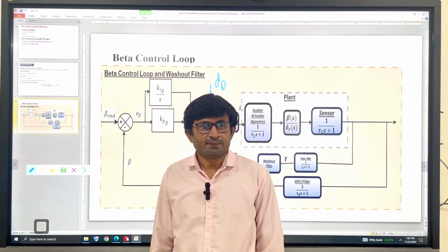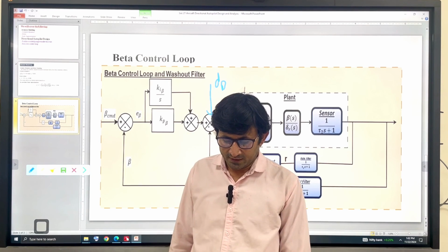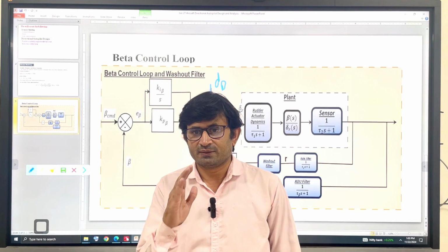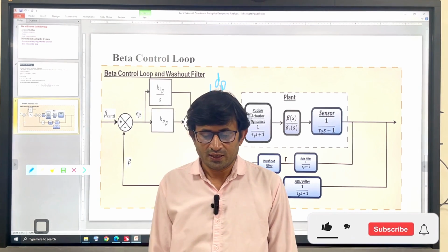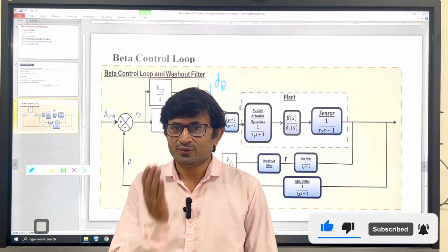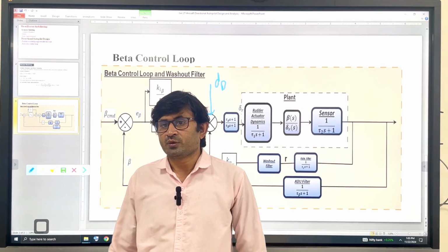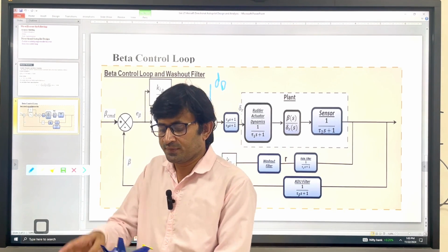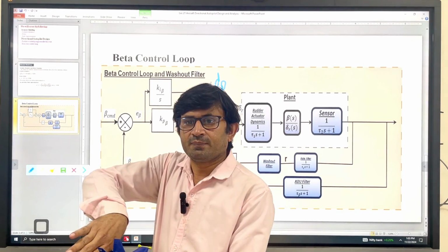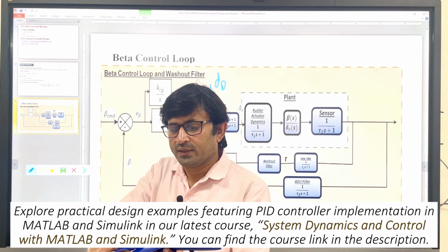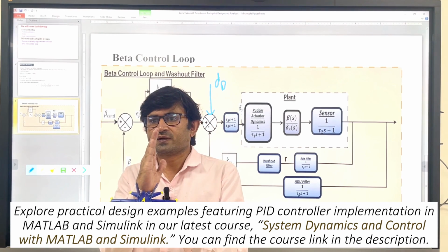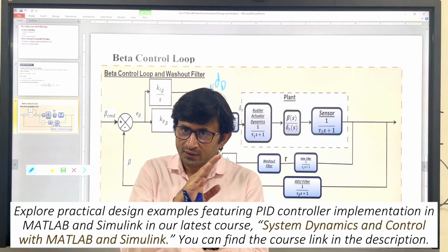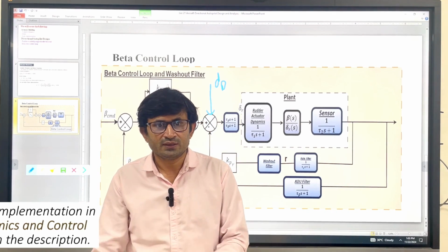That is why, when the pilot is sitting, the pilot uses the pedals, right? If you deflect the right pedal, the right rudder is deflected in this direction. And if you deflect the left one, the left will be deflected. You can have a feel for this. You can put the elevator vertically up and it becomes the rudder. When you pitch the elevator up, the aircraft will try to go up, right? Down, down. Similarly, if you deflect the rudder in this direction, the aircraft will go in this direction. If you deflect the rudder in that direction, it will go in that direction. So you can have a feel for the rudder in this way.